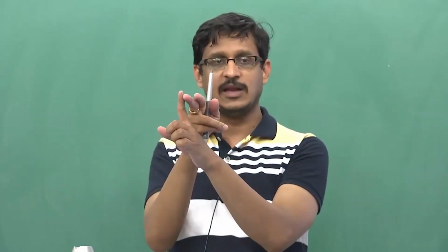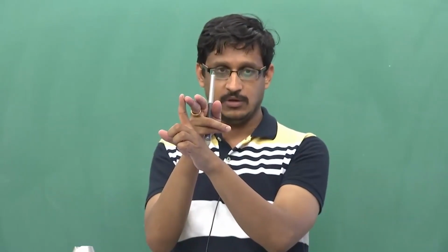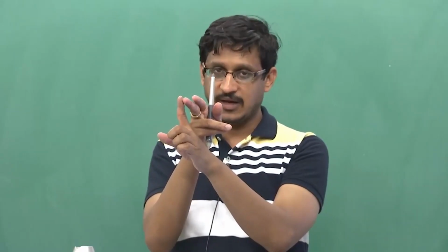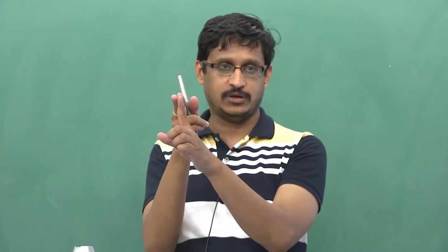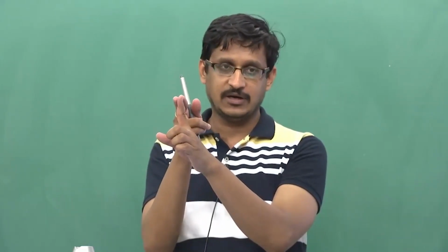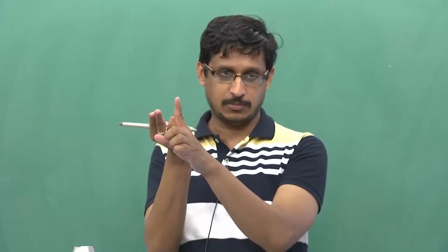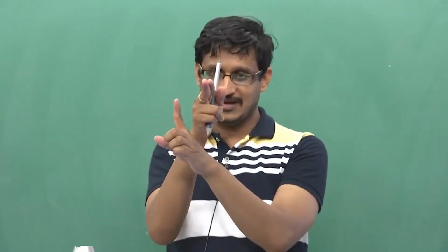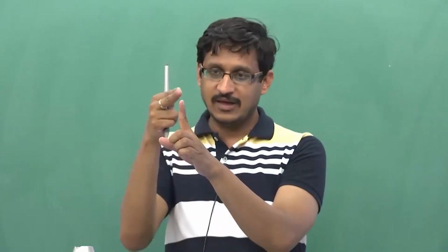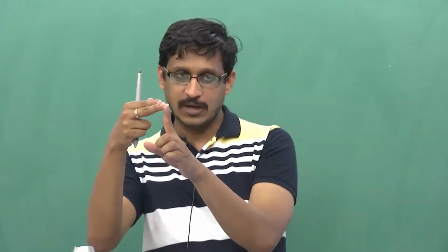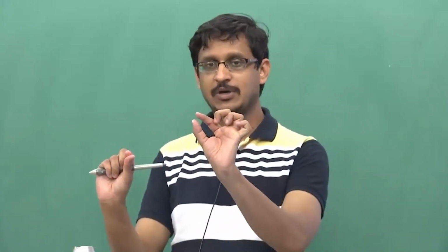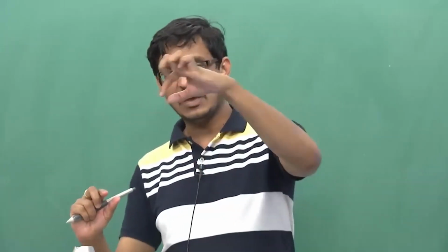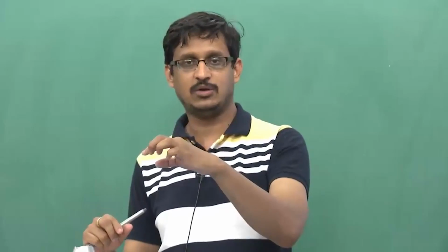Okay. So, let us say some value here which is Ez at R equal to A. Now, Maxwell's equation tells me that the field must be continuous at this point, because the tangential electric field across two dielectrics must be continuous across that particular boundary. Therefore, at this point if Ez has dropped and it has become Ez1, then the new field must take off from that point and decay as the radial distance increases. So, you have to just adjust the amplitudes of the decaying constant as well as the amplitude of the J0 or J1, J2, depending on what mode solution that you are looking for. Okay. So, that is essentially what the boundary condition does to you.